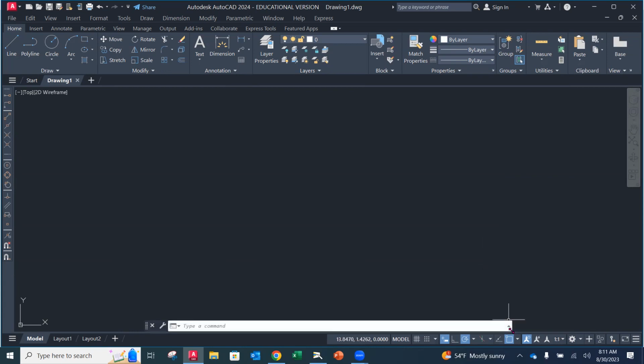I'm going to click out of there. I can always turn those off, so I have no object snaps on. Okay. So I tend to leave them on unless they get annoying and I need to turn them off. But then I have my object snaps over here to override, remember. That's why I pull those out. I think that's it for right now. So we should be okay. Those are the things that I can think of that we want our environment-wise to be all set.